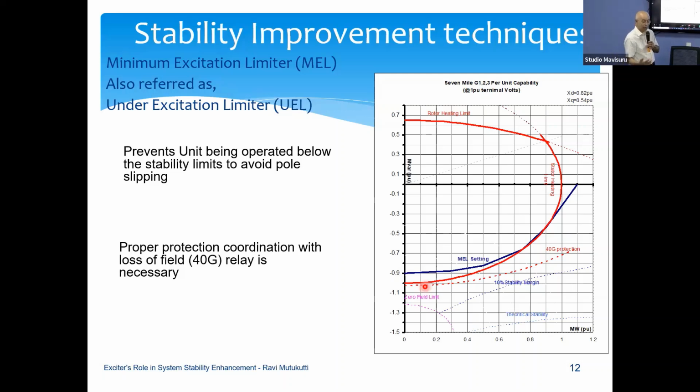And if it operates, we will find why protection operated, why other preventive actions did not prevent that protection operation. So in this case, one of the preventive actions is the under-excitation limiter. So like I said, smaller XD values are more stable.